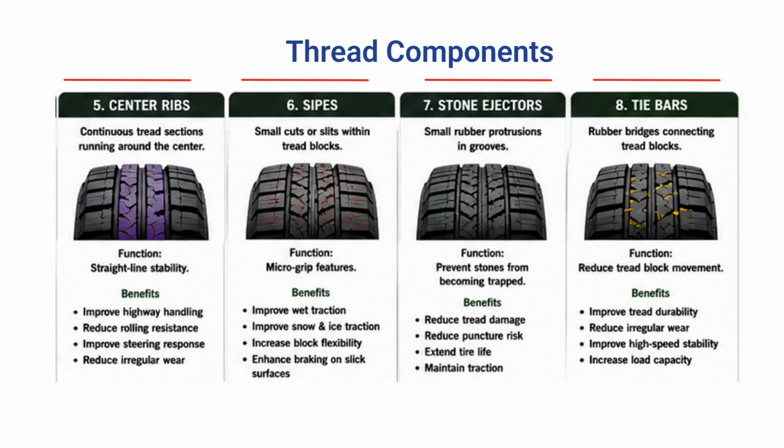Finally, tie bars are rubber bridges connecting adjacent tread blocks. They reduce excessive block movement, improve high-speed stability, and help prevent irregular wear. They can also increase tread durability and load-carrying strength. Together, these features fine-tune tyre behavior for stability, surface grip, damage resistance, and long-term performance.